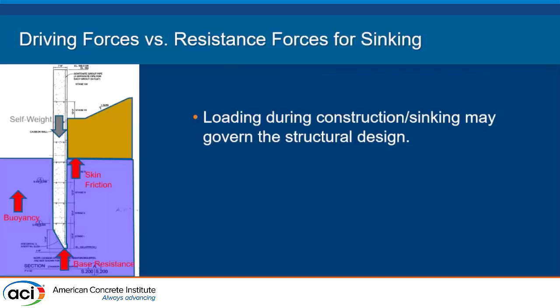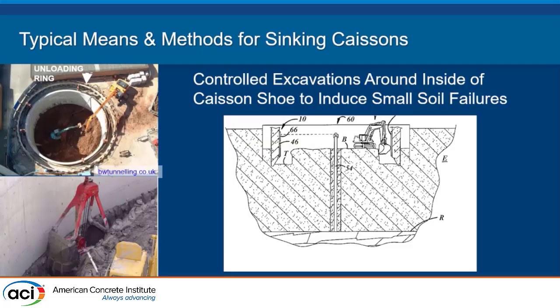It really involves a lot of soil structure interaction, geotechnical work that you have to team together. Very complex soil structure interaction modeling that you could do. You have to deal with the self-weight, overcoming the buoyancy, the skin friction, and the base resistance. So that's just the basic concept. As long as it's big enough, it's going to go down. You'll see that they take these walls and taper them down to a very small bearing area. And what they do in construction is they start to excavate and create soil bearing failures, and that's how they control the sinking process.